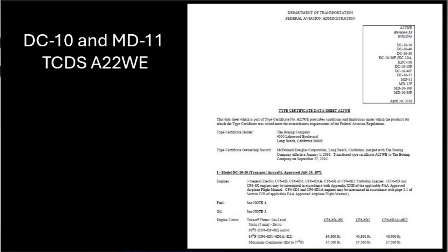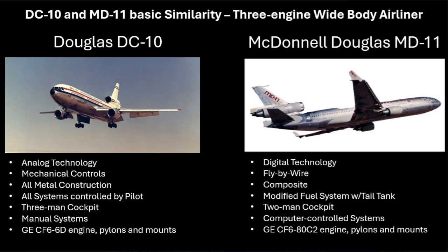on January 1st, 2010. Now, from a distance, the DC-10 and MD-11 look similar, but visually up close, the MD-11 has winglets, a belled number 2 engine inlet, a smaller horizontal stabilizer, and a longer fuselage. And despite any family resemblance between the DC-10 and MD-11, there are no similarities that have anything to do with engine mounting, which is in question in the UPS 2976 accident.